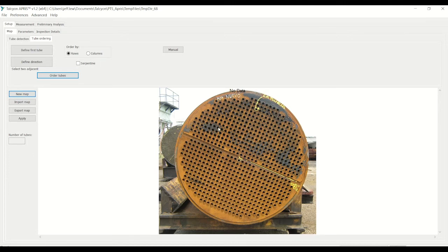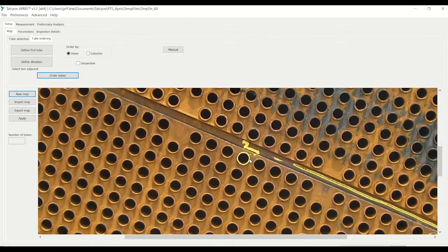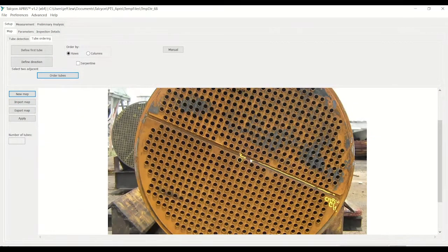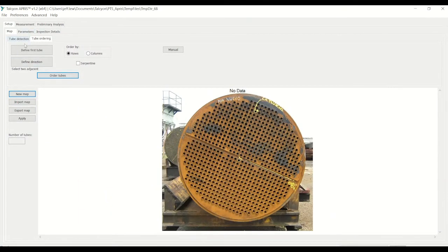This is one tip that you need to remember: always put your mobile phone or your camera in the middle of the tubes so that you can get equal diameter. Also set the resolution to the highest so you can have the best resolution like this. Now the first step, I shall set the region of interest.